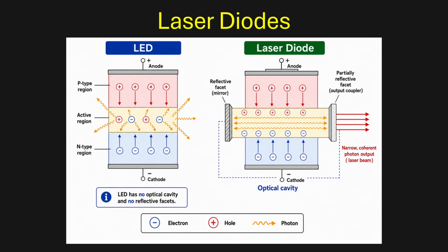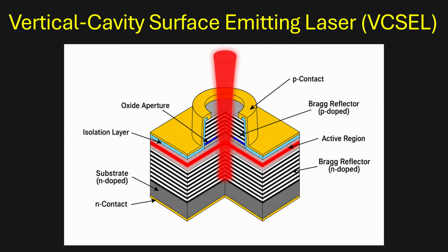Specific types of laser diodes limit the range of frequencies and optical modes in different ways. Vertical cavity surface emitting laser, VCSEL diodes, are used for short distance multimode fiber. In these designs, the optical cavity and emitted laser is perpendicular to the semiconductor layers. This differs from the parallel optical cavity in edge emitting lasers. VCSELs typically use gallium arsenide in the quantum well emission layer, which produces 850 nanometer near-infrared light.